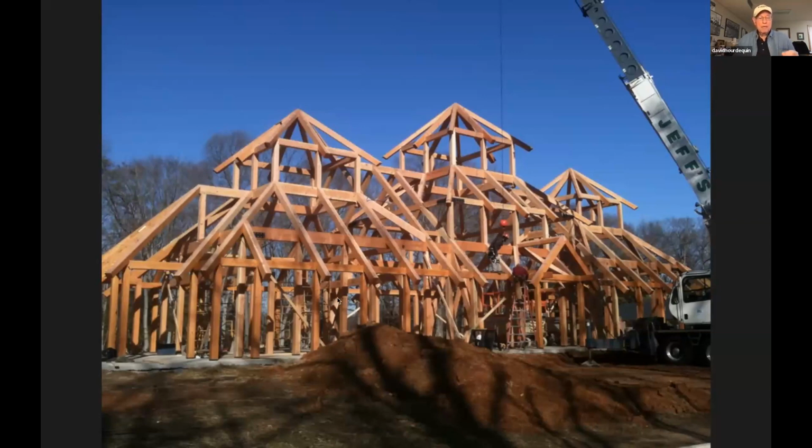And then on the inside, there's usually a 5/8 or 3/4 inch gap spacer made out of oriented strand board or something of the like between the timber frame post and the inside face of the frame wall. That strip goes up the entire length of the post. I wish I had a detail, and I can't sketch here, but I'd show you. Let's say the post is 8 inches thick. Well, that continuous piece of oriented strand board will be about 4 inches wide up the entire height of the post. That gives you an opportunity to tuck interior sheathing like drywall or 1x tongue and groove behind the post, so as the post moves with change of moisture content, no joints open up.